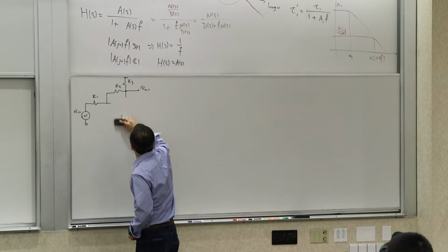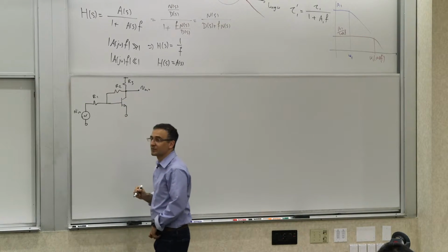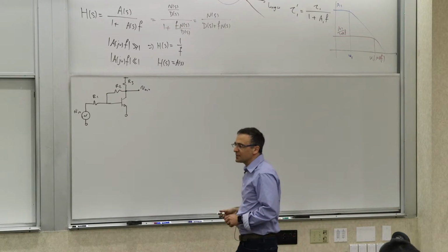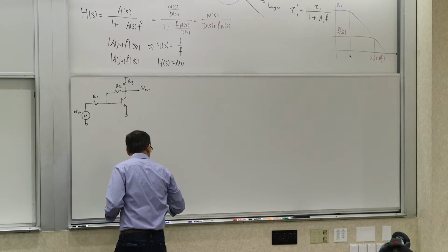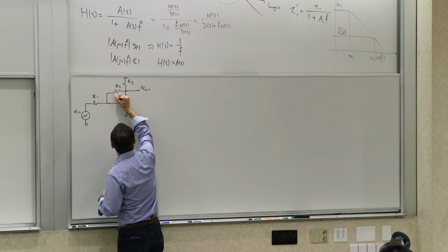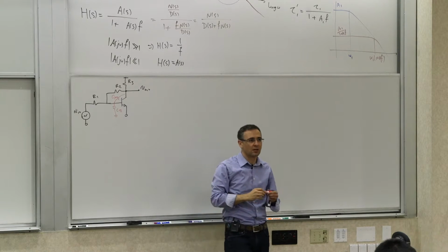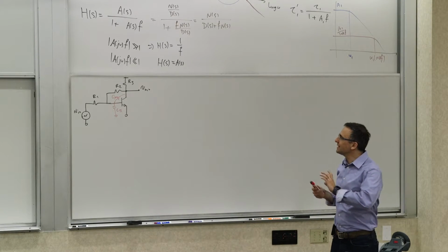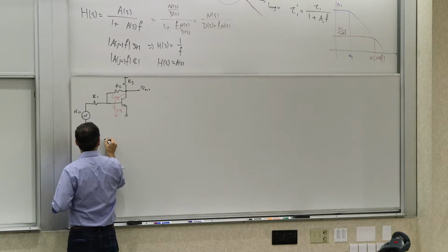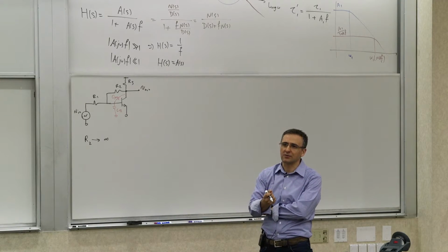It's a funny looking stage. Okay. All right, so this is what we have. Again, now let's assume that we have two capacitors, C mu and C pi. You want to take these two into account. So let's do it for two different scenarios. Scenario one is basically when there's no feedback, meaning R2 is infinity. If R2 is infinity, we know how the circuit behaves, right?